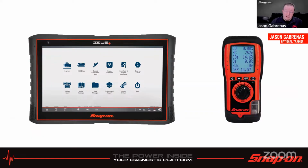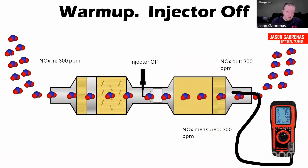To reliably diagnose one of these systems, you need at least a scan tool to be able to check data. But it's also a good idea to be able to double check the data because, like I said, the computer can be fooled sometimes depending on how that NOx sensor is working. So one good way to do that is a 5-gas analyzer if you have one of those lying around. And if you don't, there's also a specialized one we'll talk about a little bit later. We released it, I think, last year or the year before, that reads only NOx. It reads only NOx, so we can judge what's going on coming in and out.